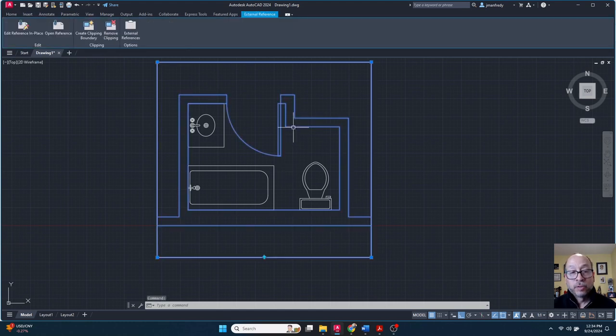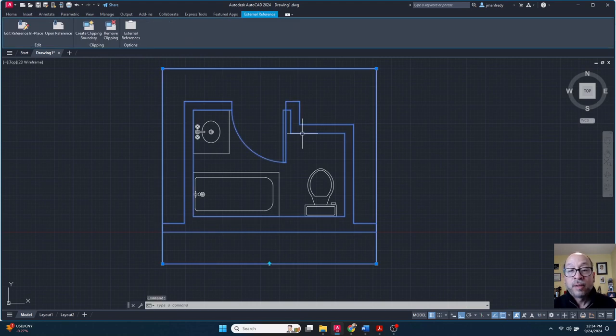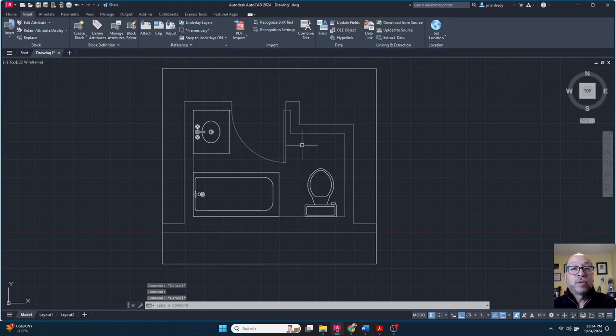The architectural drawing is this file here, which happens to be an XREF. So normally, you'd have to wait for the architect to send you a revised file. And once that file is sitting in the folder where this file was previously located and replaces this XREF file, then next time you open this file, you'll see those changes show up right away.